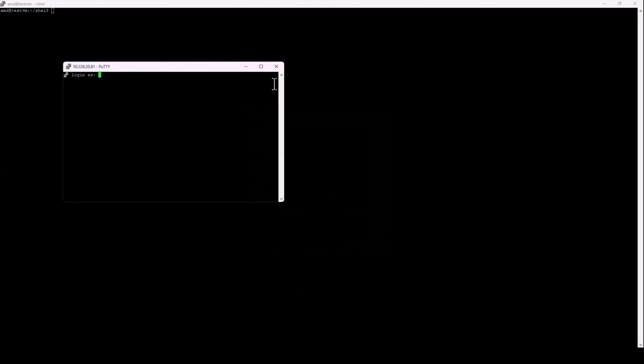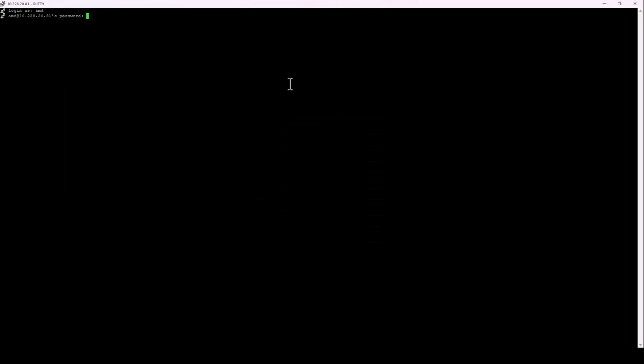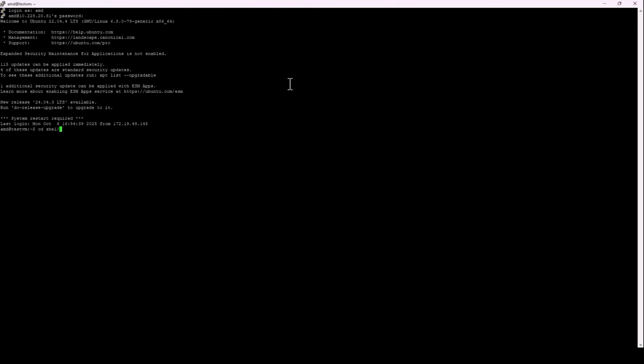Now, the Linux device tree can be created using genMachineConf utility. To do this, the Yocto project environment must first be set up. Note that a different shell environment should be used, so be sure to start a new environment. To set up the Yocto project environment, the first step is to set up the repo tool.